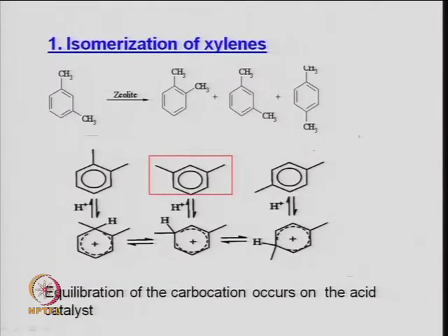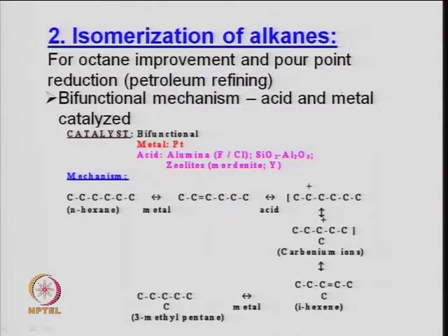These are some reactions generally shown in isomerization. Depending upon the catalyst used, one can have the process in terms of the concentration of ortho, meta, and para-xylene. So these are a kind of selective, and shape selective zeolite materials are preferred here. The same holds for isomerization of alkanes, where we need to look at a higher octane, in order to produce more and more high octane gasoline.